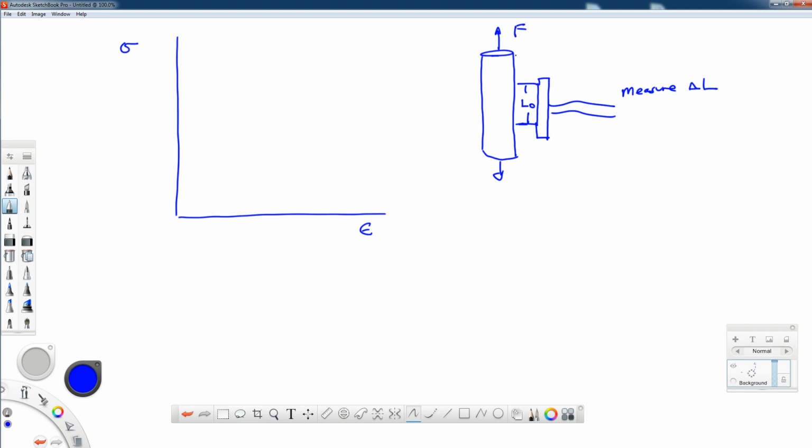Okay, so what I mean by that is if we were to look at the force versus displacement curve that I'll draw over here, if there's no displacement, there's no force. There's a little bit of displacement, there's more force, and initially it's kind of proportional to one another. So double the displacement means double the force. And so this curve kind of comes along as kind of a straight line for a lot of materials. We'll talk about some things that happen when we start to have yielding, but maybe it does something like this, and maybe it's a peak and it comes down and it breaks.